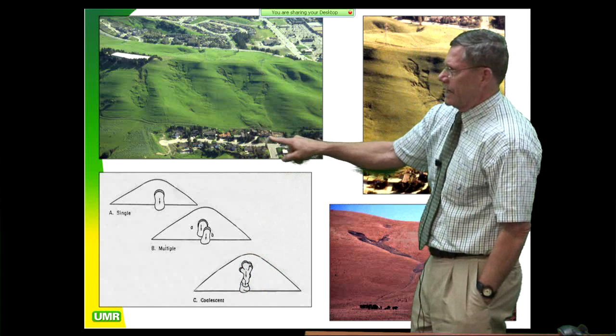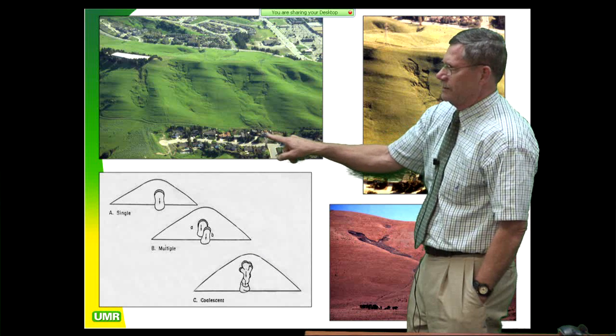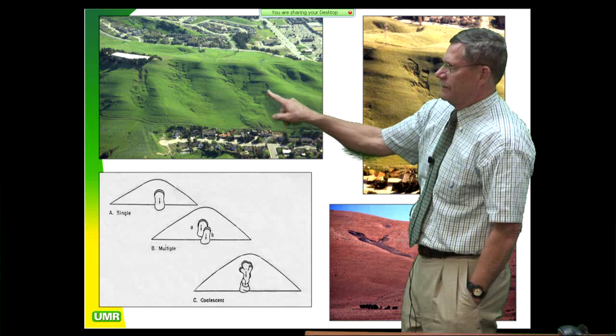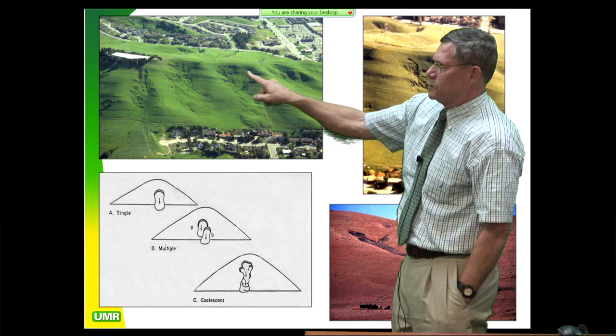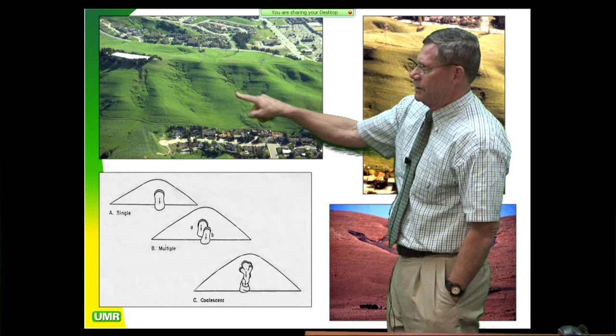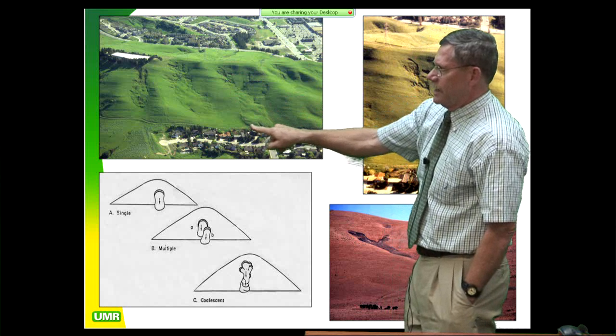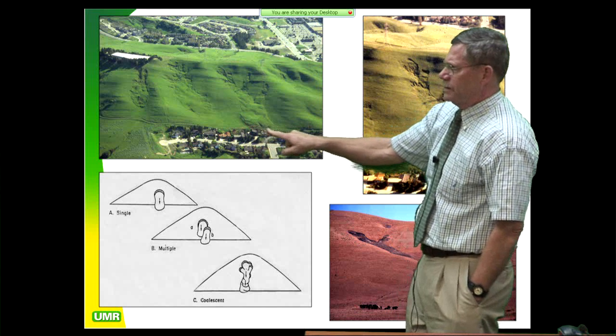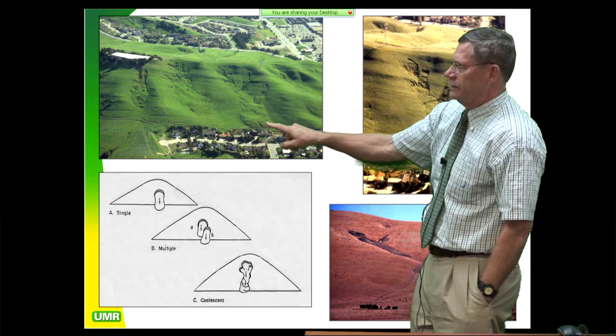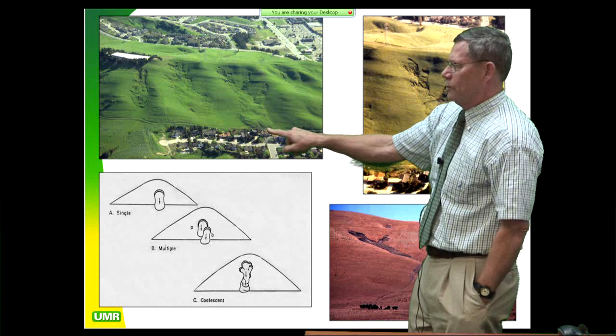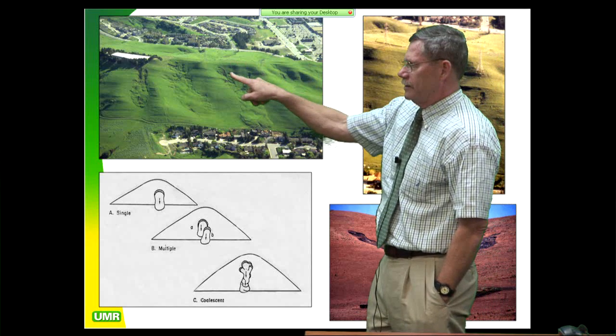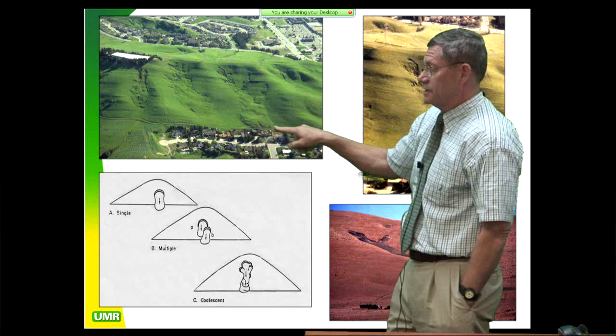And here's a real one. There you go. You got the houses right here. How would you like to live right here? I wouldn't want to be there. But anyway, look up here. You have this whole mass coming here. You got these rabbit ears coming all the way up to the top. All that stuff is coming down here. And you got passive earth pressures down here. So if you're going to try putting a wall in here, that's the worst place to put the wall, believe me. Put the wall in up here, but not down here. It's not going to be easy.